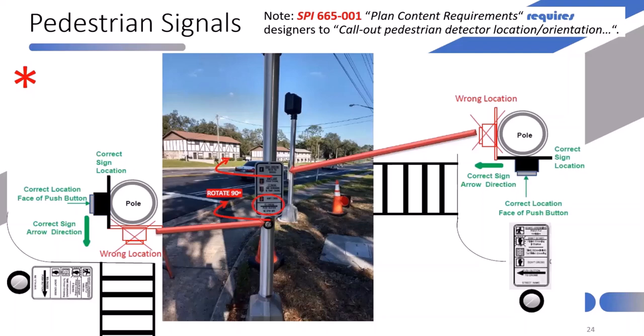And the reason for that national standard from the MUTCD is because the button placement provides that non-visual, physically detectable information that clearly and effectively communicates the direction of the crossing for someone who has a visual disability. It's an MUTCD standard because it's meant to be consistent across the country.